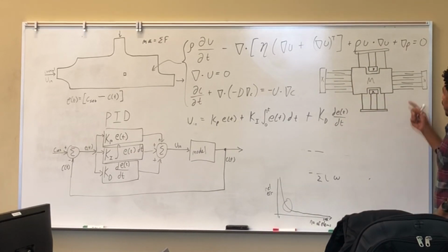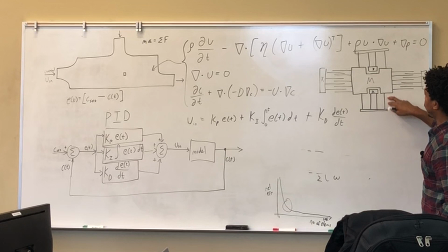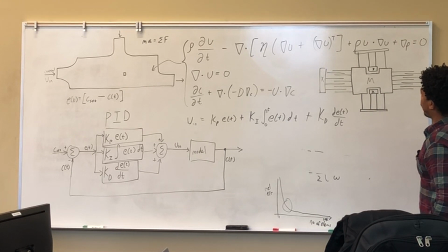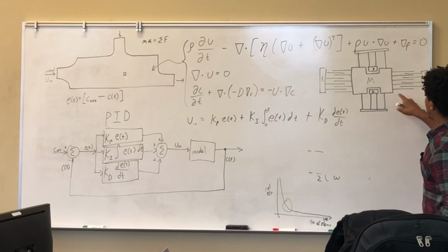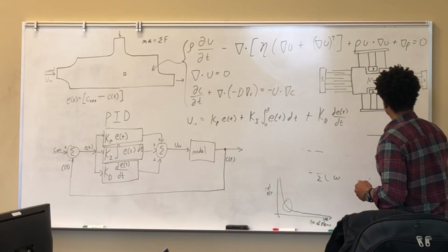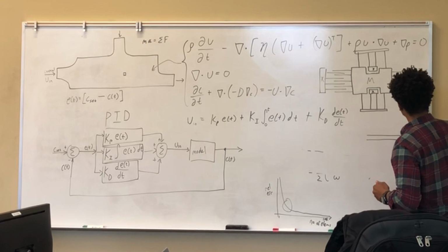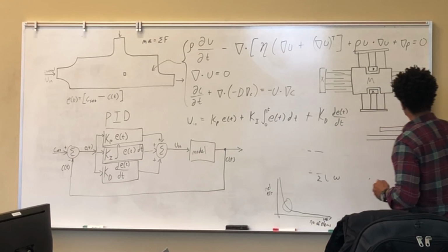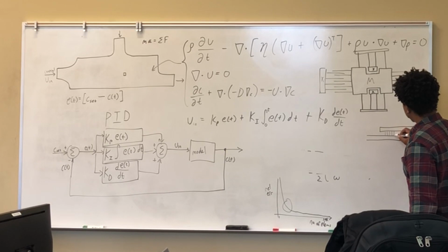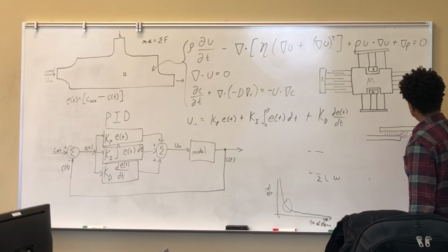We'll look at how to determine the energy of the system that's stored in the electric field. We'll also look at the energy that's stored in the mechanical structure itself as it goes from side to side, and we'll compare those things. We'll also look at the charge density, and we'll show that if you were to enlarge this comb drive right here, that one comb finger, and here's the other one on top of it, the fields look kind of interesting, where the field lines in between are quite parallel to each other, quite constant. But as you get to the edge right here, they start to flare out a little bit, like this. Okay, it's like a fringing field effect.